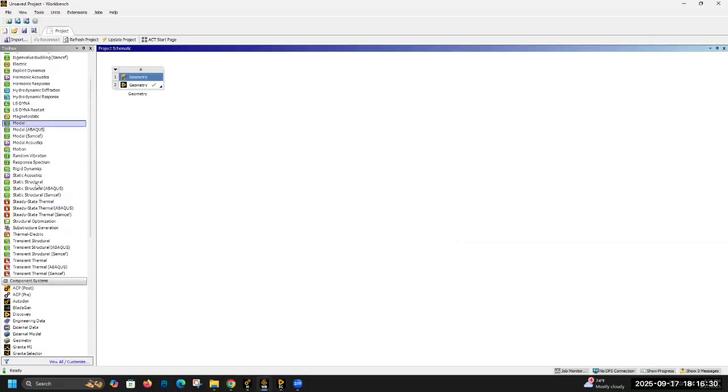So first thing, similar to what we've always been doing, is drag and drop a static structural. Oh, and with the step file, sorry, I don't know if I explained, but when you import it in, after you download it from your downloads folder, just drag and drop the step file in, and that should work pretty well. That's another pro tip. It's better to have step files when you put it into ANSYS. The other file types, it kind of reads them, kind of not. It's hit or miss, but with step files, I've never had an issue whenever I exported. So I recommend that. You can see this is our geometry that we imported.